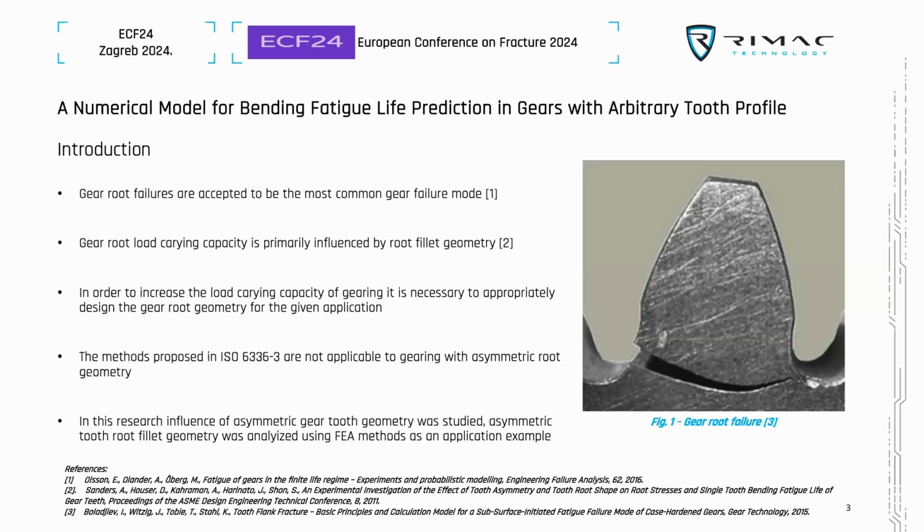Unfortunately, for such geometry of a gear, its load capacity cannot be determined using the standard approaches outlined in ISO 6336 or similar international standards. Usually this is approached using different numerical models, and analytical approaches are very rare and usually not experimentally validated. In this research, the influence of asymmetric geometry will also be taken into account using the finite element approach, but with a certain addition of a numerical model built to evaluate the data given by the finite element analysis model.